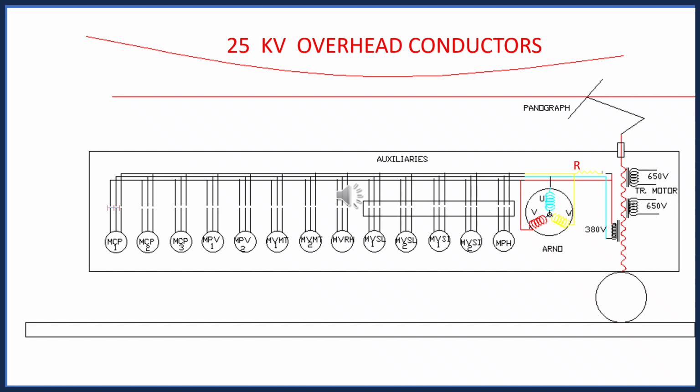These 5 auxiliary motors need immediate action when the loco has started. So we are closing all the switches of these directly. Before doing any other operation, first you close these 5 auxiliary motor switches, then you switch on the loco circuit breaker, and it will start all these 5 auxiliary motors.